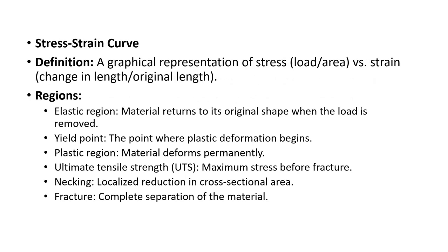Then a very important factor is the stress strain curve. Stress is nothing but load upon area and strain is nothing but change in length divided by original length. The stress strain curve is a graphical representation of stress, that is load upon area, versus strain, that is change in length divided by original length. Again I will repeat, stress is nothing but load upon area and strain is nothing but change in length to the original length. So through that the stress strain curve is plotted.